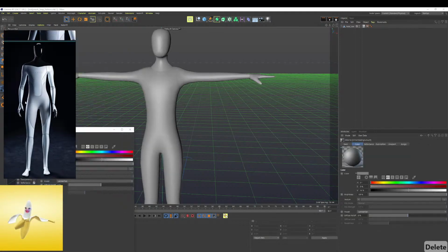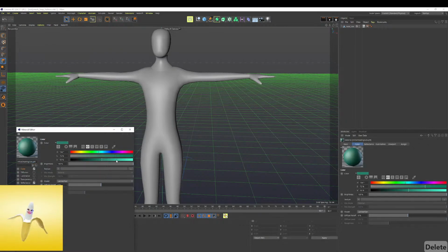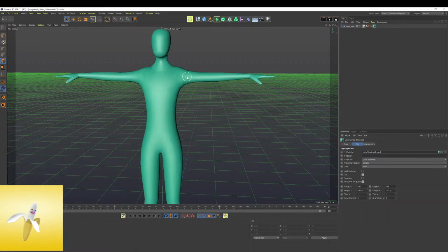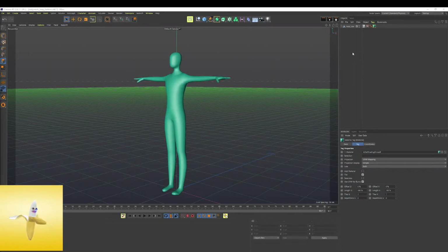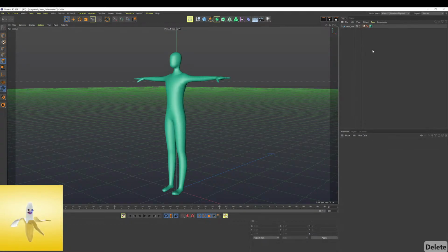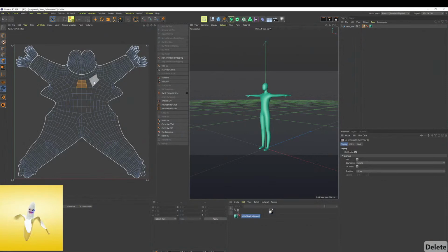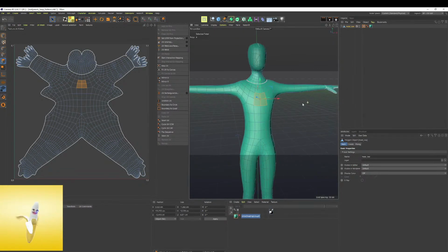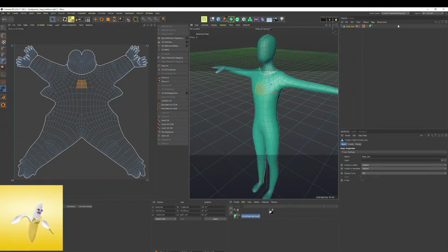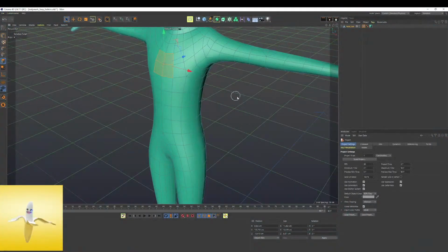So I'm going to apply a random material. This is not the paint color. I just apply this to make sure that Substance Painter knows that my model has a texture applied to it. I'm going to get rid of any unneeded data and make sure that my UV maps are still there. Yep, UV maps are still happy campers. Good. All right, so now that we have a model that is modeled and UV unwrapped, we can now paint it inside of Adobe Substance 3D Painter.